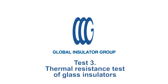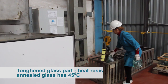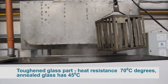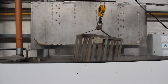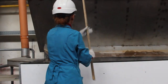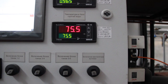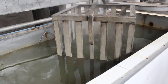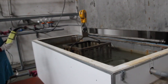Thermal resistance test. High thermal resistance of toughened glass, 70 degrees centigrade. The annealed glass withstands only 45 degrees centigrade. Toughened glass part guarantees correct operation of insulators within the temperatures range from -60 degrees to +50 degrees and at rapid temperature change. Let's heat glass parts up to +73.8 degrees centigrade and then quickly put them into a tank with cold water with temperature of +3.6 degrees centigrade.